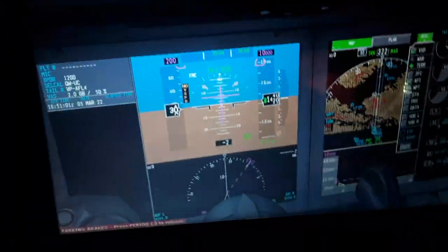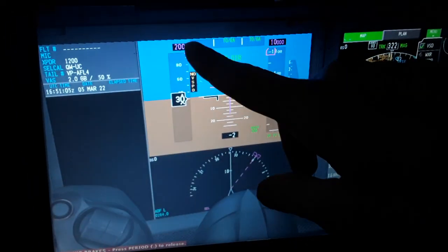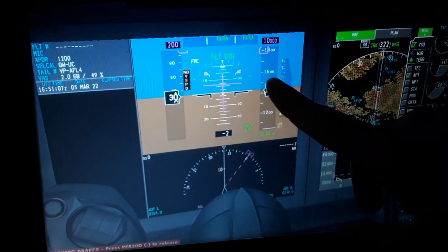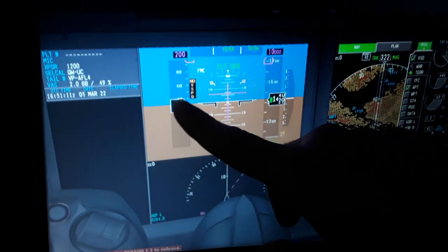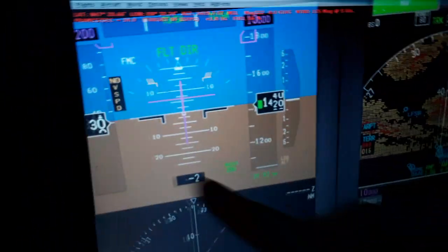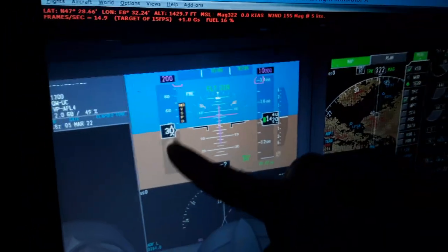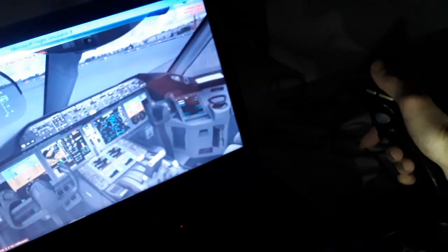You can see we have the airspeed tape over here. We have the airspeed indicated, the airspeed selected from the autopilot flight director system panel, and barometric altitude. I'll talk about this a while. When we fly, you can also see the stall speed displayed with an amber and red indication just below the airspeed. You need to pay attention, because what actually makes the aircraft fall from the sky is the stall of the wings.